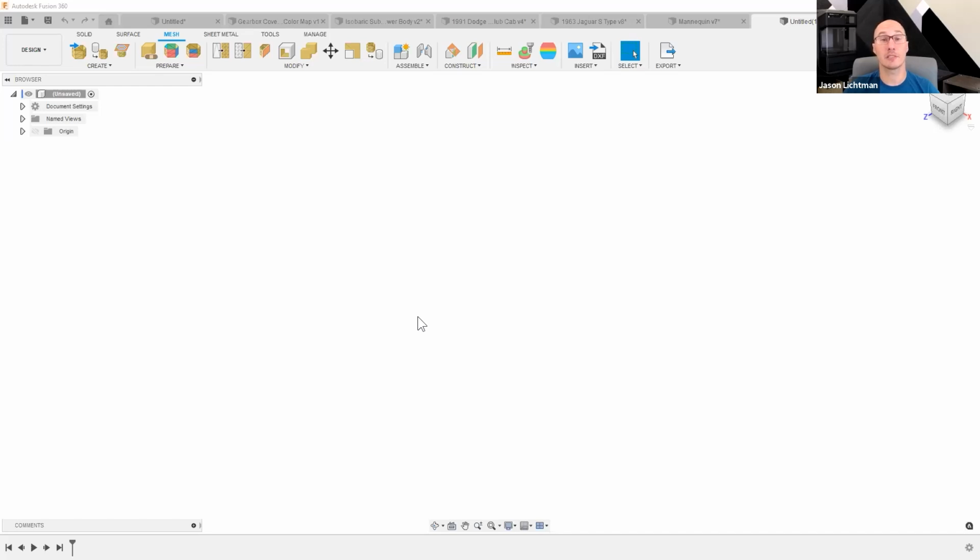If you do, however, have a solid body as a result and you want a surface body, just switch to the surface menu and select the face and hit delete. That will delete that face and therefore convert your solid body into a surface. I hope that helps.